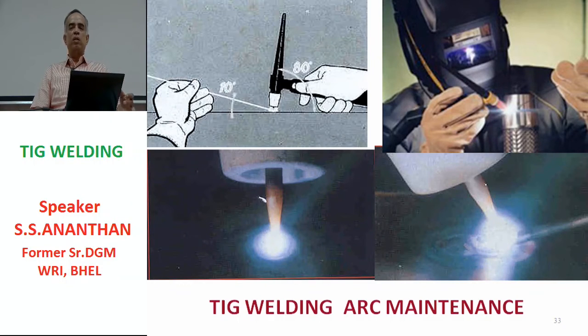Now he holds the torch at a particular location without moving at the start, and slowly gives a circulation movement as the heat buildup takes place in that particular area. Once sufficient heat buildup is there, where the top surface of the material starts melting, he inclines the torch as shown in the second picture, and then he starts adding the filler wire.